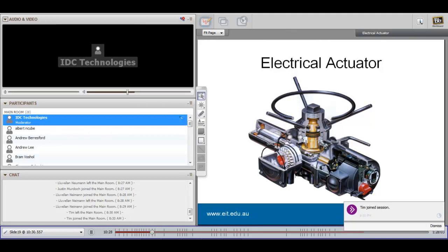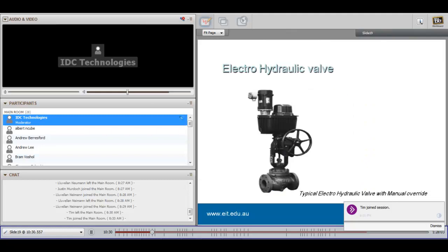Right, so we've dealt with pneumatic, we've dealt with electric. The only thing that's left is going to be the hydraulic actuators. Hydraulic actuators will give us a fast action. They're very, very suitable for remote areas. They do have a fail-safe action, especially if you've got the accumulator that goes hand in hand with them. They're very small, they're powerful devices, they are quite expensive.